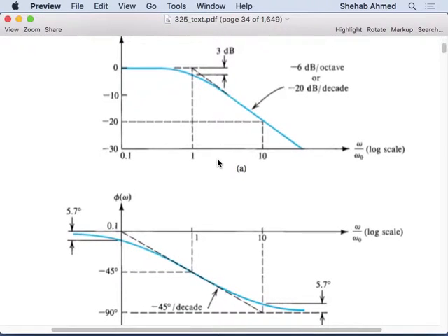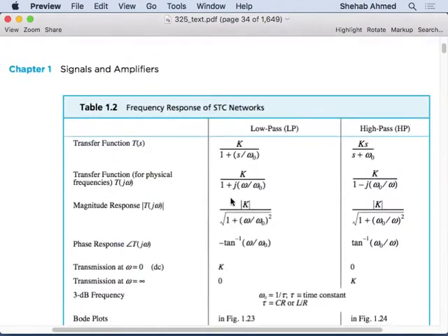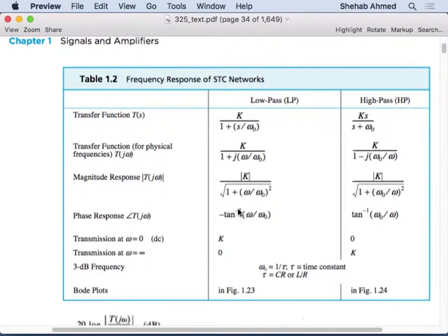In phase, if I ask you what is the phase at DC, you have to go look at the expression for phase of the signal. So you would put in whatever frequency that signal is at. For example, the sensor has an input frequency of 10 squared radians per second, and your corner frequency is 10 to the 6 in this case that we calculated. You will have to calculate this and tell me what the phase difference is between your input and output. If I ask what is the phase of the signal when you have 0 dB gain, then you would take your omega naught. Omega will be 100 omega naught. So it's inverse tan minus inverse tan 100 that will be the phase in that case.